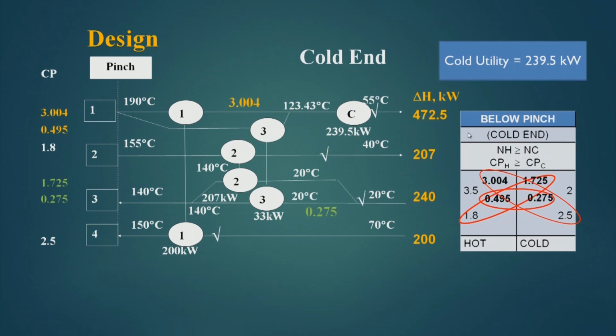the cold utility requirement was 239.5 kilowatt, and this cooler is taking 239.5 kilowatt. So, this design is complete and according to the targeted value of 239.5 kilowatt of cold utility. So, this completes this design.